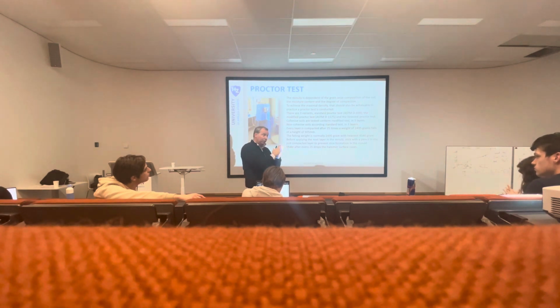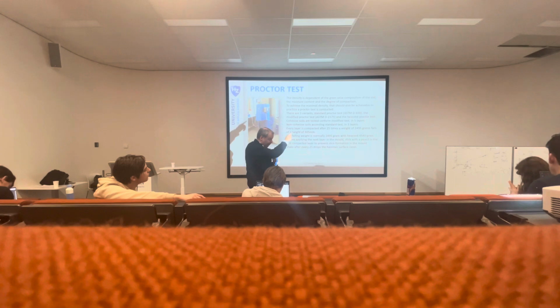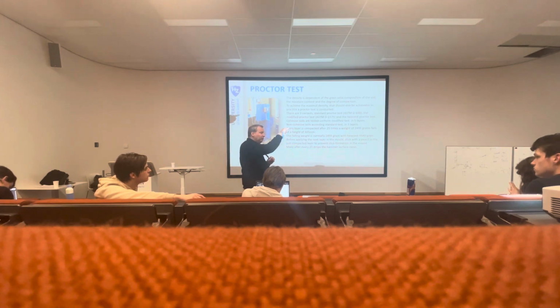And at a certain moment, if you start adding too much water and you put the dot on the screen where you have the y-axis of the density and the x-axis, then at a certain moment you will notice, oh, the density is going back down again. That's why we do those different points to make that curve possible.